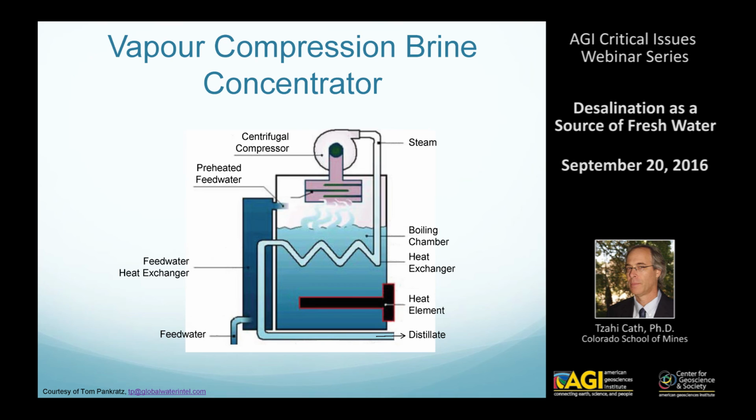temperatures. Another option of distillation processes, more commonly used and considered to have a little bit lower cost of desalination, is vapor compression distillation, where the vapors are taken from the top of the chamber, compressed with a compressor, and that enables a much faster liquefying of the water and production of distillate at the bottom, and with some heat recovery inside the distillation process.